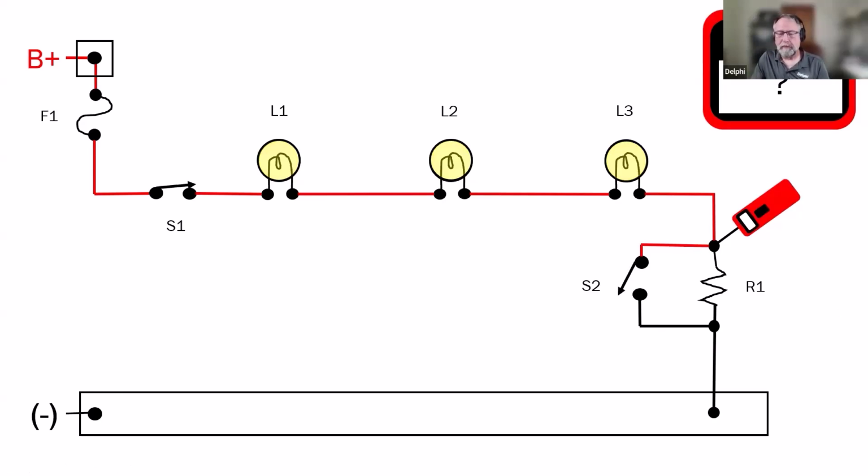Now what do you see? Is there going to be a significant voltage drop taking place across R1? The answer is yes. And we see that there's a 7 volt difference between where the power probe is contacting here and the battery negative. So we've got a serious problem going on. If we thought this was supposed to be a good ground, it is not a good ground. We've got a 7 volt drop across that, and this resistor is the problem. Notice again, the green negative is not lit, the red positive is not lit. It's somewhere in between. There's something going on there.